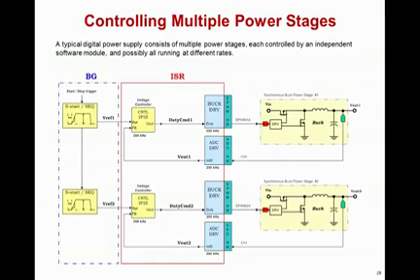This modular architecture for the software allows us to do many different things. First off, we can control multiple power stages, so you can replicate the number of blocks that you want to use, change out the type of controller perhaps, or which PWM and ADC channels you're interfacing with. You can also implement an interrupt service routine structure with a lower latency background task. This allows you to do something that's less time critical in the background and execute your interrupt service routine in a very time critical, low latency fashion.